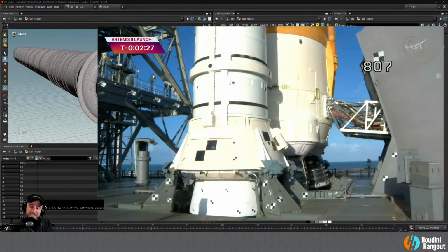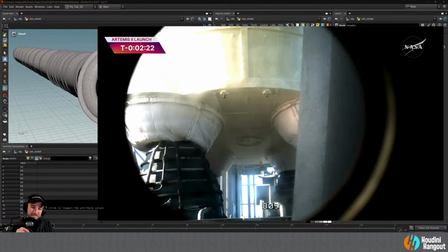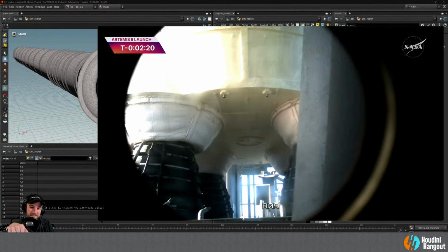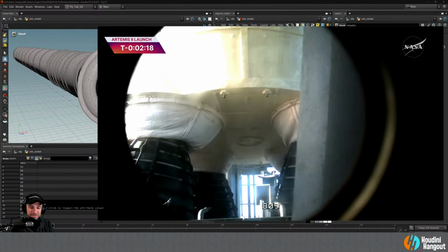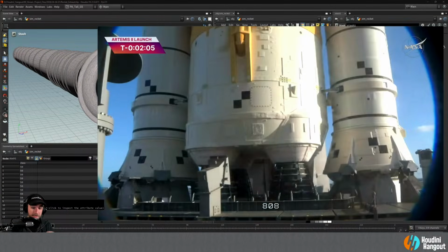You can actually see the engines there in the middle. They're doing gimbaling. They're testing, because these engines at the bottom of the orange tank can steer the rocket. So they're doing a gimbal test. They call this thrust vectoring, and they do this test on the engines. They used to do that on the shuttle as well. The shuttle had the exact same engines on the back of it, just 3 of them instead of 4. So yeah, they used to do the same test.